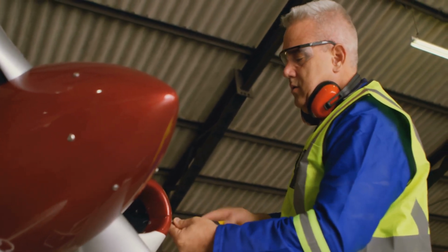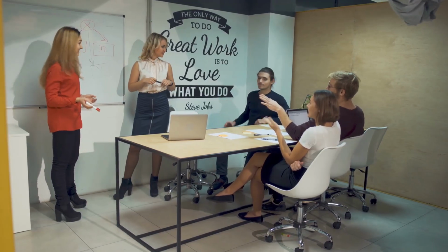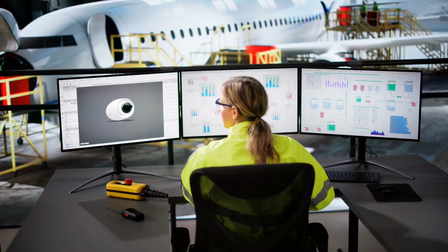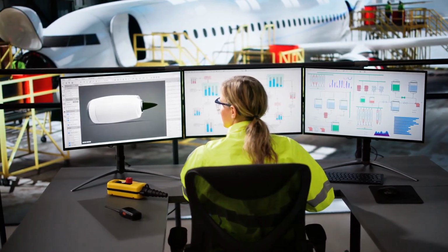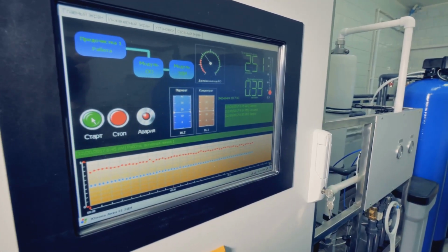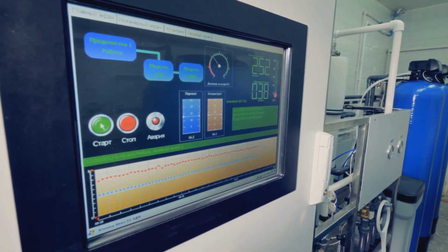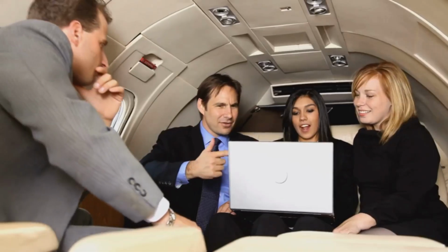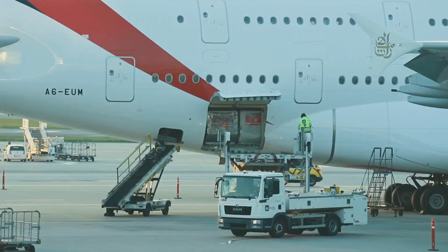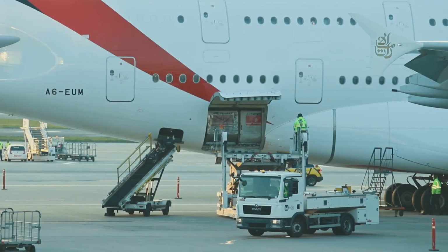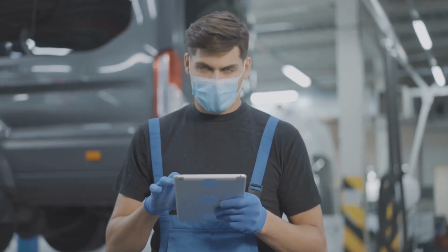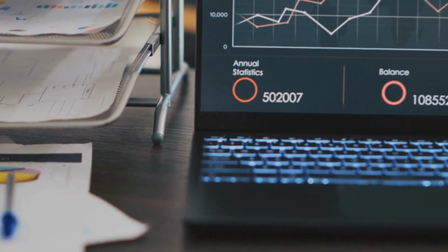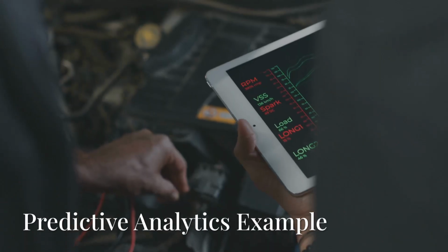Maintenance isn't reactive. It's actually strategically planned, and the supply chain is looped into every step along the way. Most airlines operate maintenance planning departments, which forecast checks using fleet utilization data and maintenance intervals. These forecasts are then shared with material planners, procurement teams, warehouse teams, and logistics and freight forwarders. Smart supply chains use MRO software integration, like Amos, Trax, or Ramco, to generate predictive part requirements.